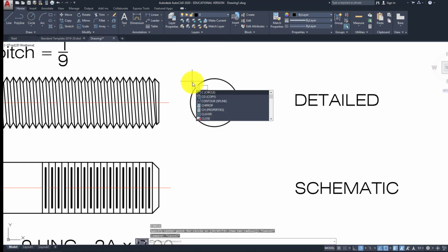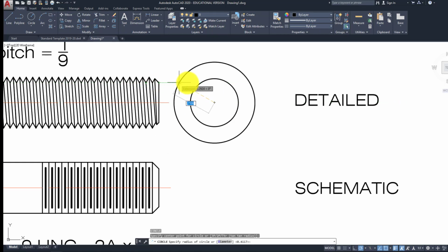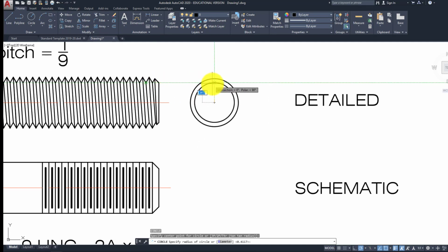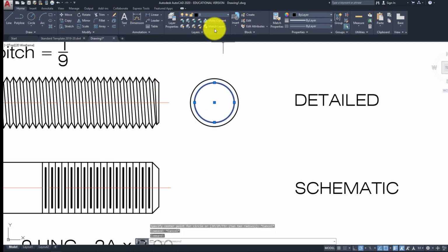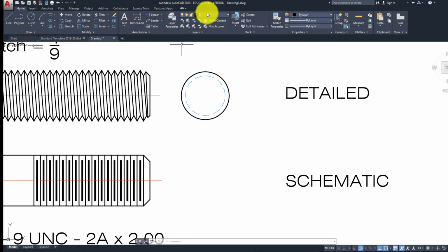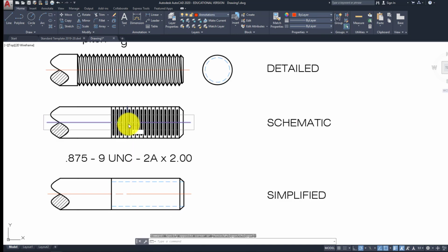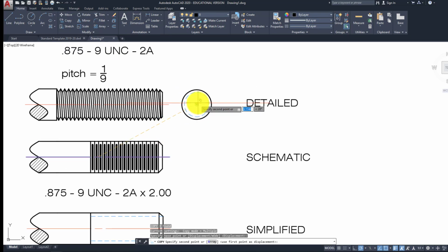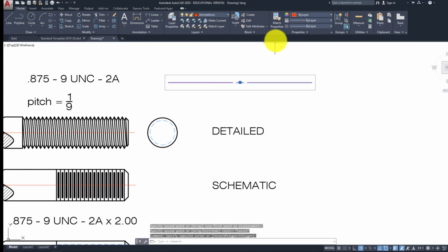So this one I've also seen differently. I've seen where people show the minor diameter like this, and they show it visible, because you would actually see this. Then I've also seen people make this hidden, because you don't actually see this and you want to show kind of separating it from either way. So I've seen it both ways on multiple drawings. For me, I think either way is acceptable. It's when you do the minor diameter, that's when you get a little different. Alright, so what I'm going to do is copy my center line over because I like to do that.